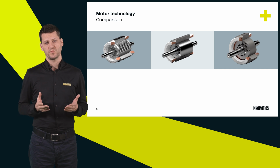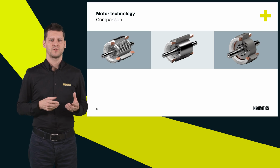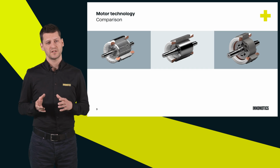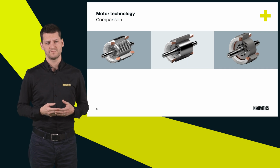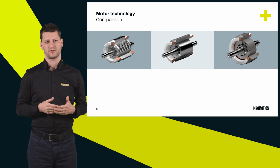What is also very important is that the asynchronous motors can be run directly online and also together with the frequency converter. But the synchronous reluctance motors and permanent magnet motors cannot be run directly online, they can be run only with the frequency converters. Let's talk first about advantages of those three motor technologies.